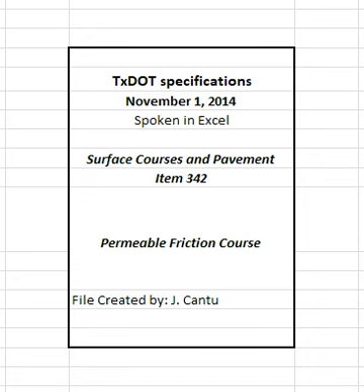4.7.1 Weather conditions. 4.7.1.1 When using a thermal imaging system, the contractor may pave any time the roadway is dry and the roadway surface temperature is at least 50 degrees Fahrenheit. However, the engineer may restrict the contractor from paving if the ambient temperature is likely to drop below 32 degrees Fahrenheit within 12 HR of paving.